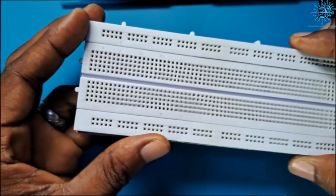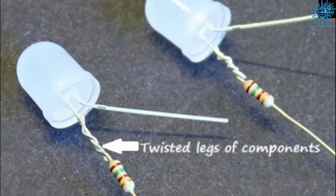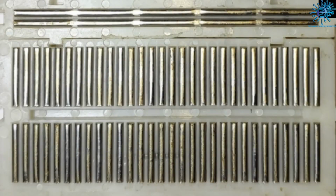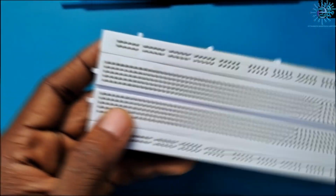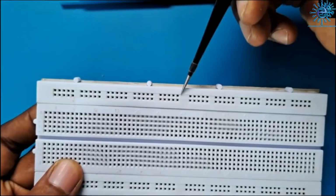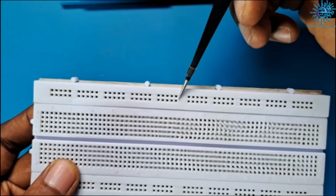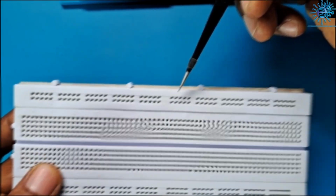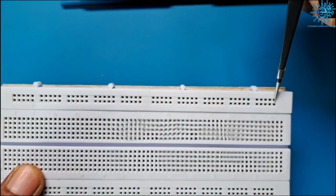Without a breadboard, we may need to twist the legs of our components when we connect them. But with the help of these metal connections of the breadboard, we can connect the legs of our components without damaging them. On this type of breadboard, all the holes from here to here are connected, and then we have a gap here, and all the holes from here to here are connected.